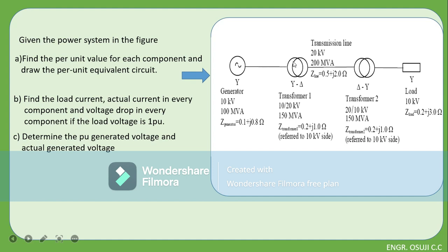The impedance in this region. And we told you that this is region 1. Look at also for this transformer, where is it referred to? It says refer to the 10 kV side. Where is the 10 kV side? This is actually 20 kV. This side is the 10 kV side, which is the secondary side. And this region is region 3.